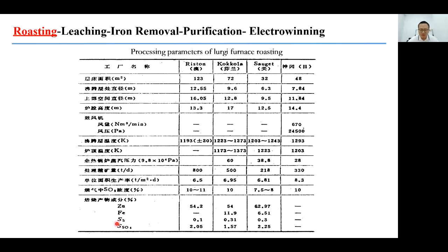Some are still sulfide forms, like zinc sulfide, in the core part of the particles, which didn't react with the oxygen. There is also some copper sulfide, which migrates into the core and stays in the calcine. And the sulfate is mainly contributed by lead sulfate as the coating layer or the outside layer of the calcine.